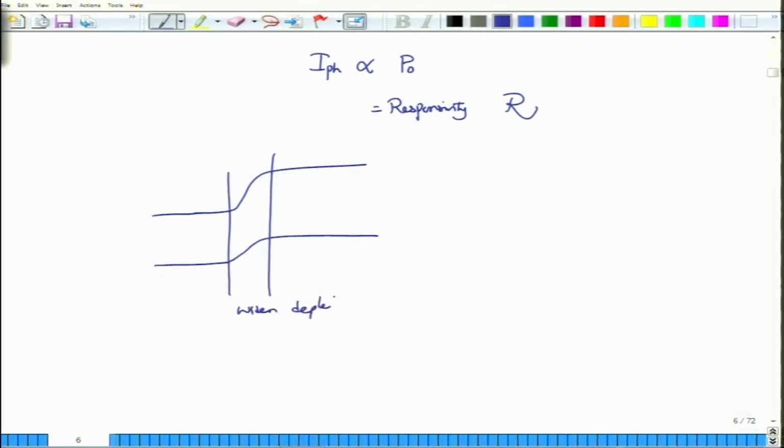So, when you widen the depletion layer and then create an electron and hole pair here by shining light onto this depletion layer, because this is the N type region and this is the P type region, there is a built-in electric field which is very strong, okay, and it is strong because you have also increased the depletion layer and increased the reverse bias.